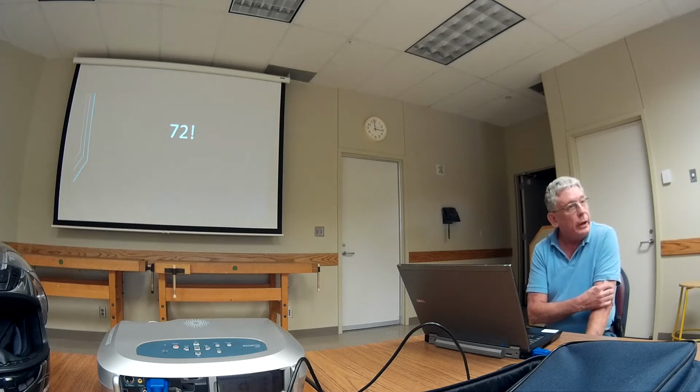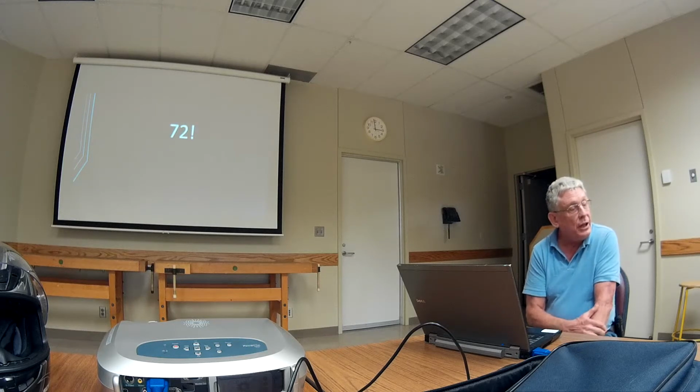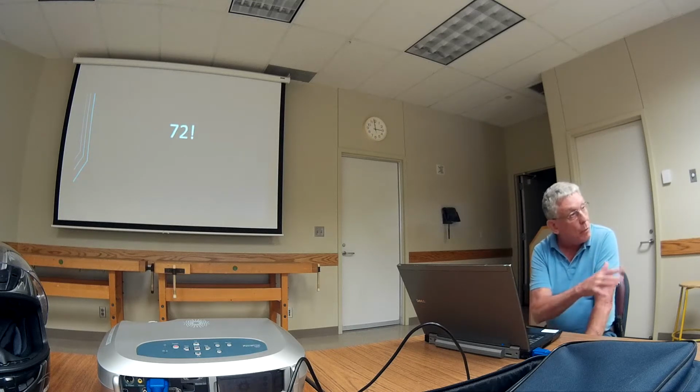Common base is very good. I use a lot of that for front end stuff. The downside is the input impedance is even lower typically. I guess that's right, because it's coming in. Yeah, and it's tough to match, but the same kinds of principles apply. Common base is great, and they're more stable.